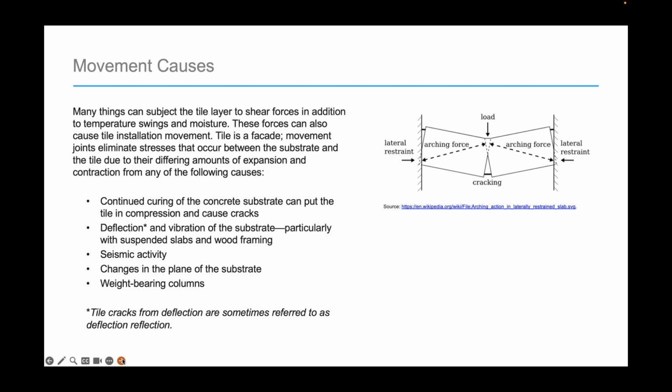Continued curing of the concrete substrate can put tile in compression and cause cracks. Deflection and vibration of the substrate, particularly with suspended slabs and wood framing. Seismic activity, changes in the plane of the substrate, weight-bearing columns. Tile cracks from deflection are sometimes referred to as deflection reflection. And you can see on the diagram on the right where it shows the load in the middle pulling away and where it's cracking.